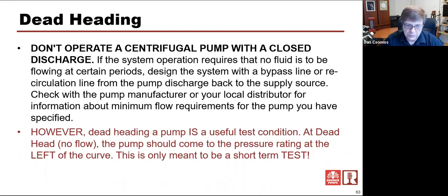This again speaks to deadheading for any long period of time, but it's okay to take it to a short-term deadhead. And by short-term, I mean as quick as you can make it, 5 seconds, 10 seconds, and then gradually open it back up and get flow going through it again.